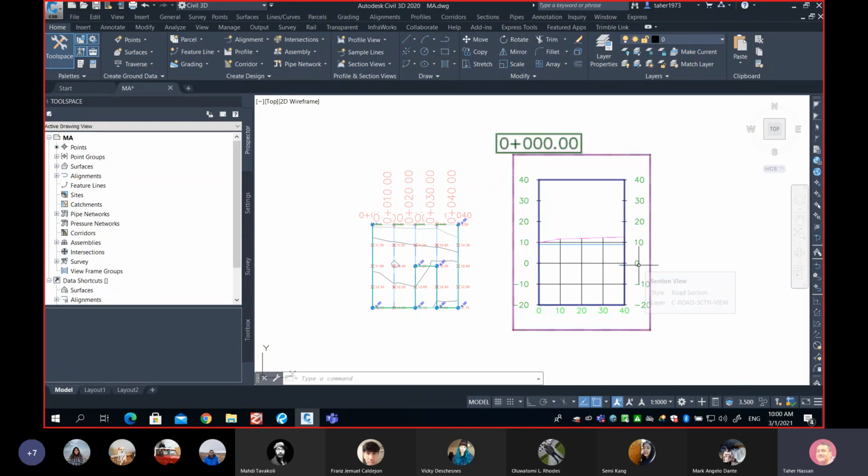Until you open it, I want to remind you of what we've been doing in the last class. We wanted to see how Civil 3D can estimate some volume for us, and we have seen two methods. Method number one is called the volume dashboard, where you need to build two surfaces. And remember, you need two, not only one, two.